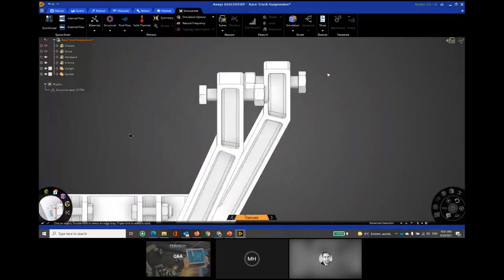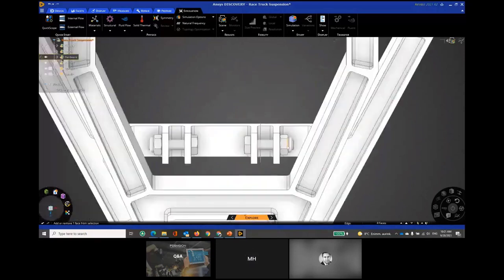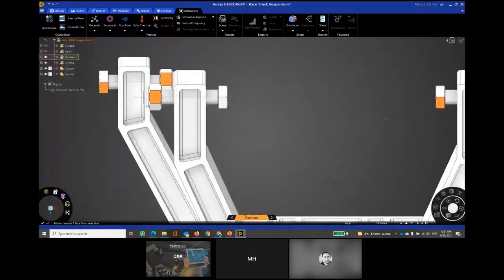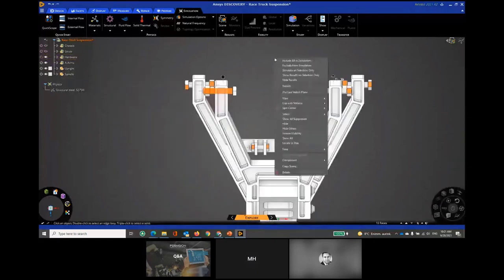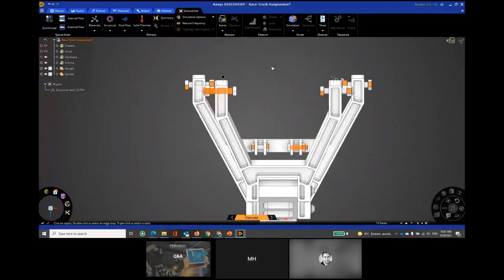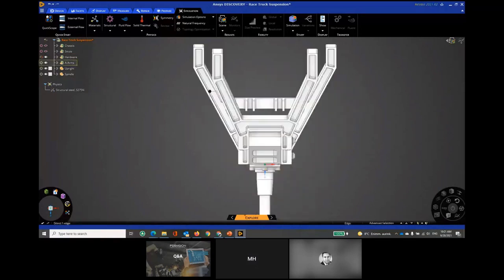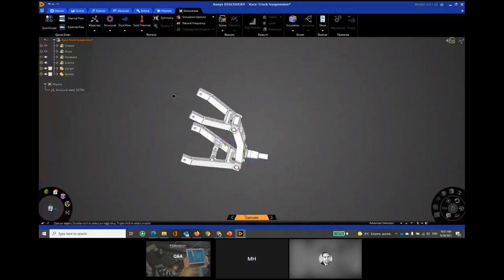Then it is enough for me to click one surface of these individual nuts and bolts, just to make sure that all of these bolts and nuts, which are not really required in this simulation, are removed. Of course, I can do this from the model tree, but it might be a bit more visual for me to explicitly exclude them from the simulation, and to keep track of what I have been doing, hide or suppress. Now my simulation geometry starts to take the form of what I want. So we have an early suspension system in here.